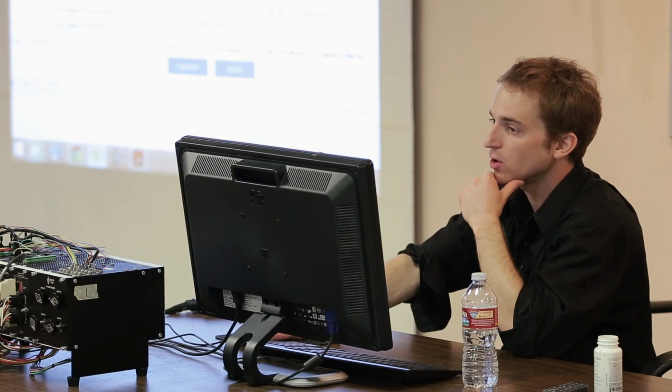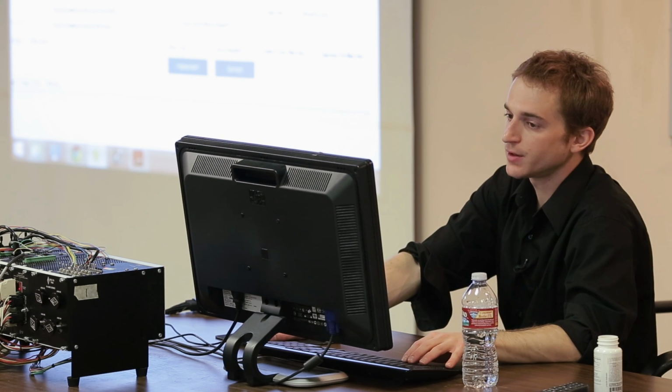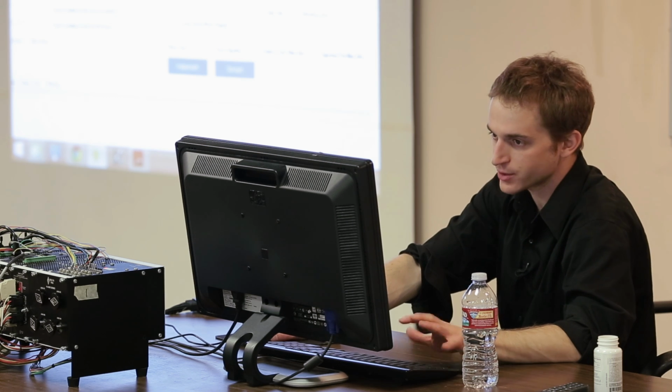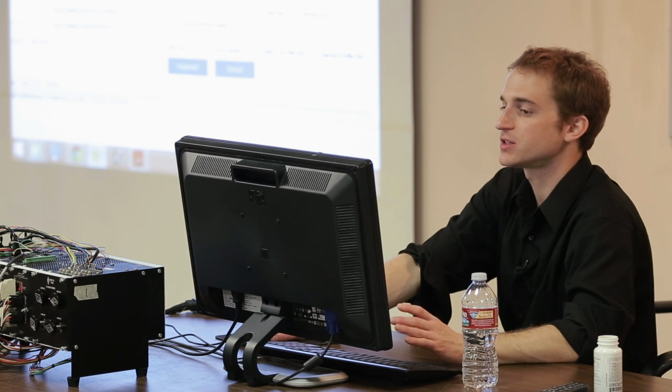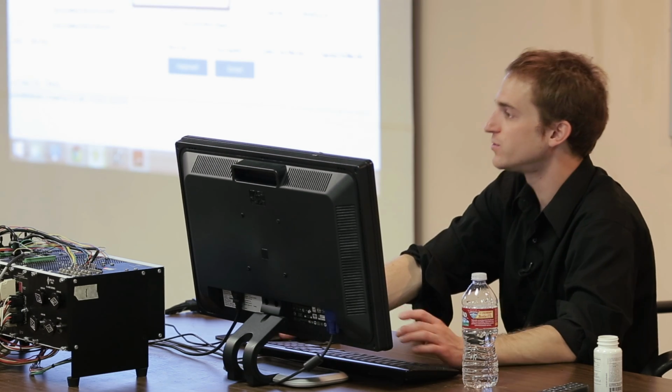So clicking on parabolic velocity, I will first set kVFF equal to kVFB. Like I mentioned a couple times, that is a good place to start, and then right after doing that, I will issue the parabolic velocity move to see where we're at.